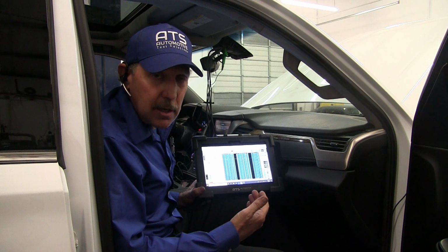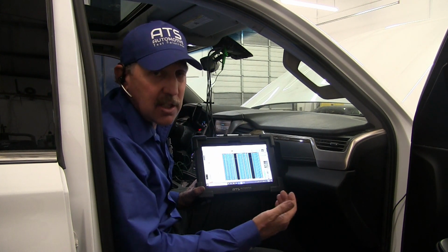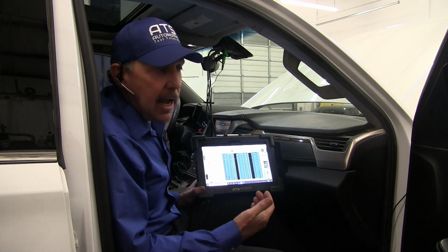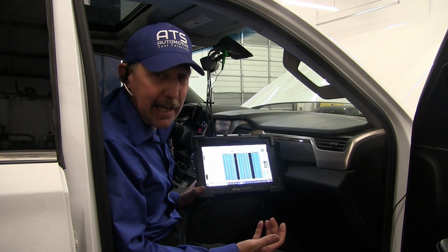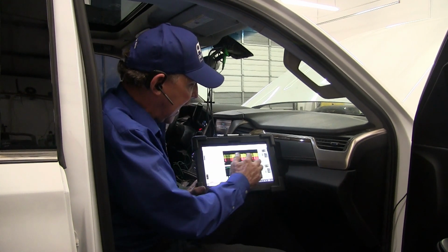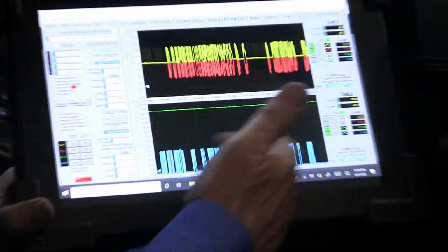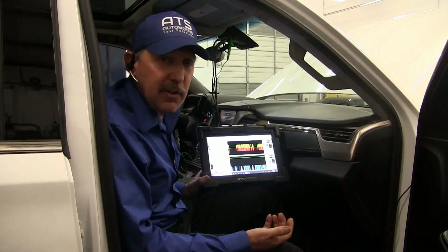So that system is sort of confusing because it makes you think that it is some type of intermittent, and then you start to look at the wiring diagrams and you see that we have CAN lines. And the CAN system, as we've already talked about, looks okay. I didn't have LAN, but in the original wiring diagram, LAN isn't even shown.